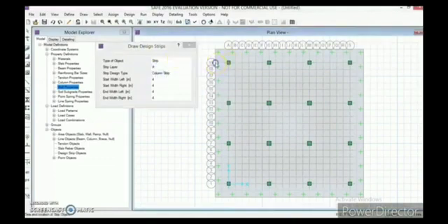So I am designing the design strip horizontally across the centers of column, and right click to exit. And now here I am designing my next design strip horizontally. Similarly, draw the design strip B vertically, starting from the top.